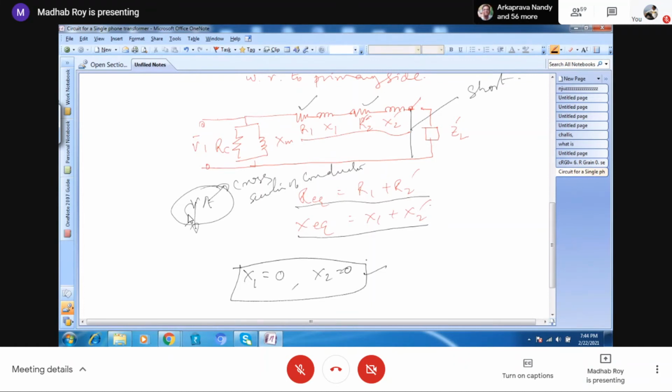But here we cannot maintain that temperature inside. No, that is not the issue. It is not only the case for temperature. The superconductor is basically a pure conductor material. You cannot use any magnetic material inside it, so the purpose of the transformer will not be served by the superconductor, because you cannot use magnetic material there, otherwise there will be no magnetism there.